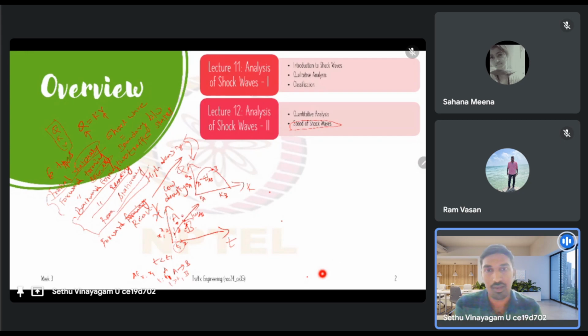So at the boundary, vehicles are changing from one traffic state to another, right? The number of vehicles leaving traffic state B should be equal to the number of vehicles entering traffic state A, right? By using that conservation law, we found that the slope, WAB, will be nothing but (QA minus QB) by (KA minus KB), right? That is nothing but the slope of this line in the QK fundamental diagram. So that's how we derived the speed of the shock wave.